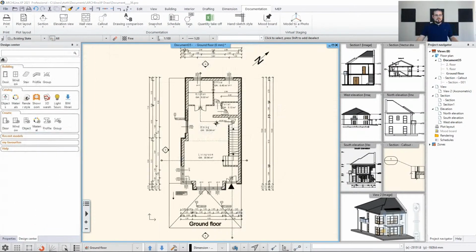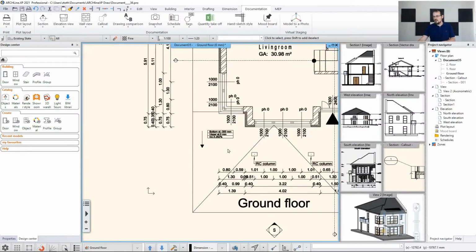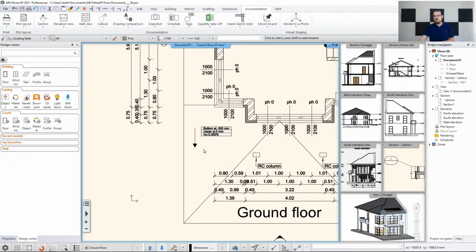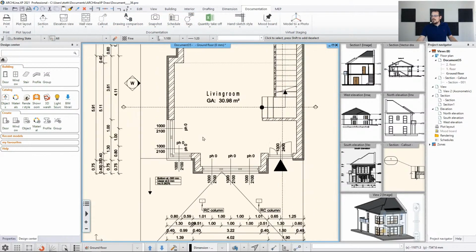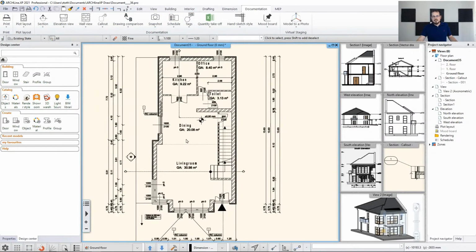particular item. We just showed you how to create information bits extractions from certain elements, and that was this thing what we did with this ramp. We showed the bottom elevation, upper elevation, and the inclination, and these are data that you didn't type in. They were extracted from the item itself. Now, that was done using the tags, but there's another way of extracting information in bulk, and for that we have the tool which we call a schedule. The method is the same, but this time we are going to work with more than one item.